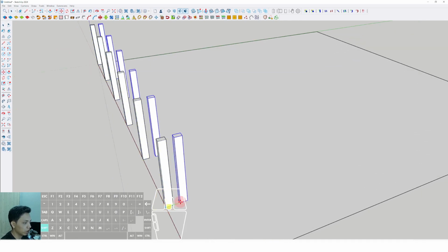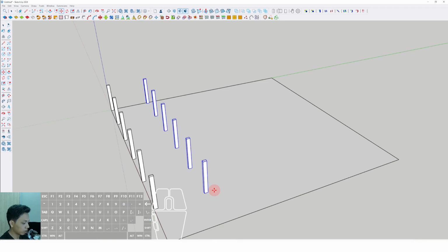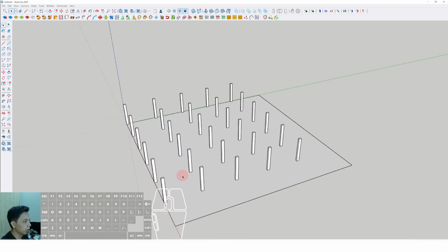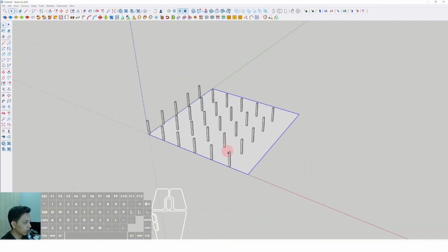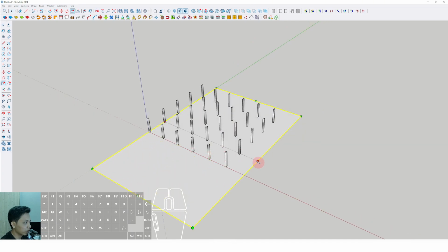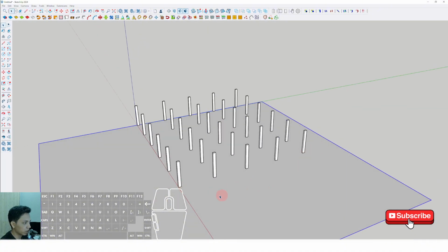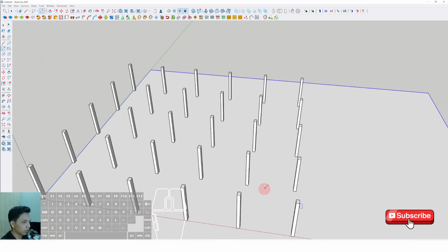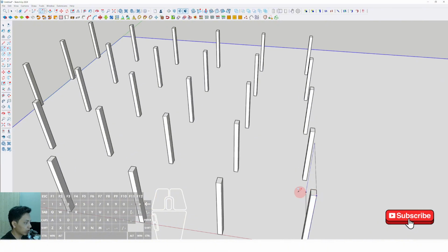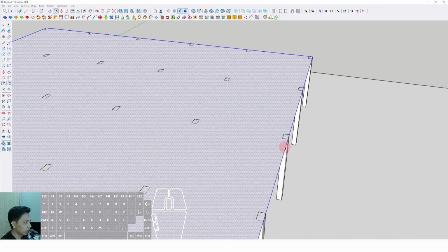Okay, I will continue. We can move and press Control and duplicate it around 8 meters. Then we type x4 and enter, so we get the grid of the column system. Then we can enlarge this base plane to make the hallway in front of this area. We select Rectangle, click on this point, then click on this point, and then we can offset it inside.